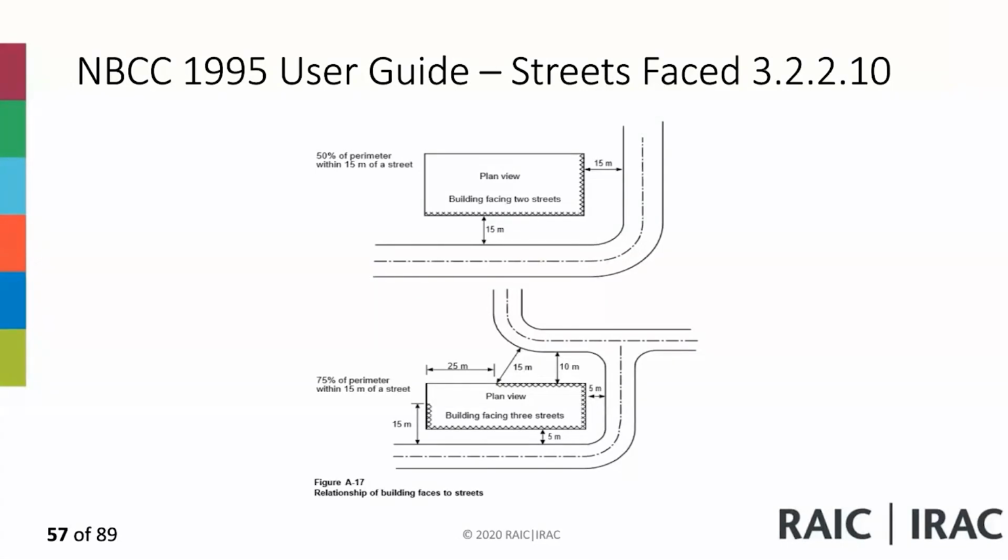But for calculating the height of the building, you have to use one grade, and that's the most conservative one. But when you have stepped buildings, the code gives you an allowance for calculating grade, and that is in 1.3.3.4. So you have to go to the provision of 1.3.3.4 and see what it is about.